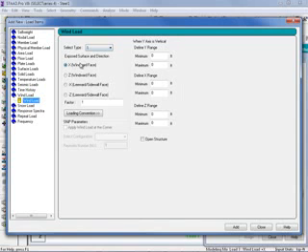We will identify it as a windward face, and we'll enter the factor. Here we will enter a factor of 1.0, and we will keep it positive, indicating that this is a force in the positive X global axis direction. After entering the appropriate parameters, we will then click Add. We will now proceed with the load items within this load case by adding some additional items to account for the leeward face and also the sidewalls.